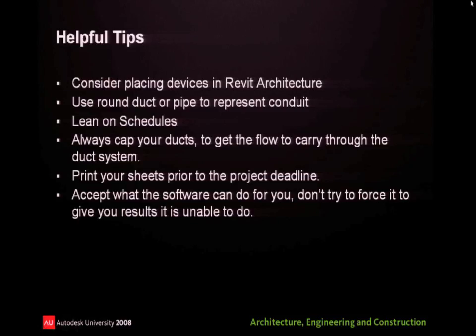As a backup plan, print your sheets prior to your deadline. Don't wait till the last day to print those sheets out, because that will give you an opportunity to go back and apply the view templates so you get the output that you desire. Bottom line is accept what the software can do for you. Don't force it to do something it's not able to do. Grow with it.